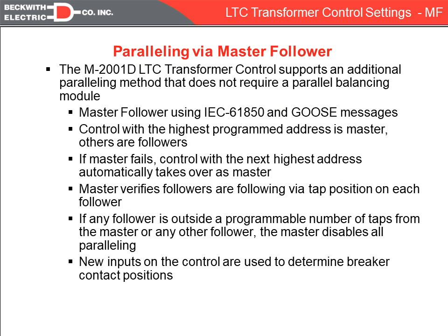A final feature that we've added for transformer LTC applications and for paralleling is we have one method, and we'll be adding a second method in the next release for paralleling using communications. So the first method is a master-follower scheme in which you would identify one of the controls as a master, the others would be followers, and the master and all the followers will be hooked up on the same Ethernet network.